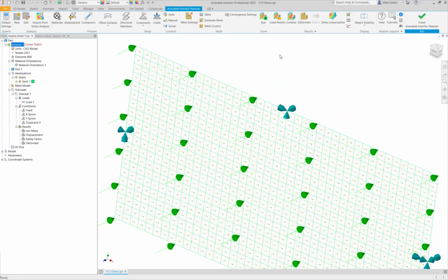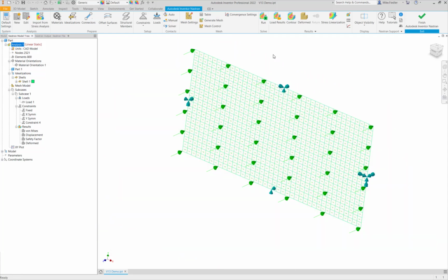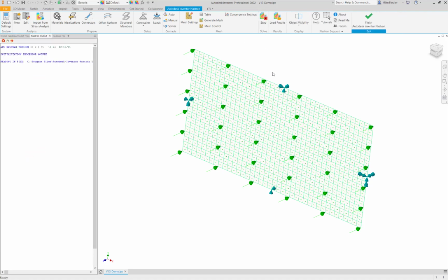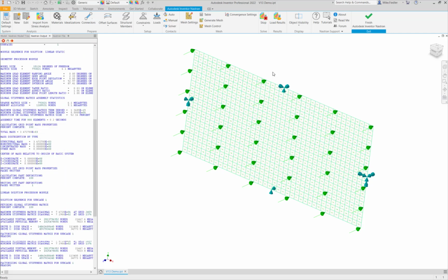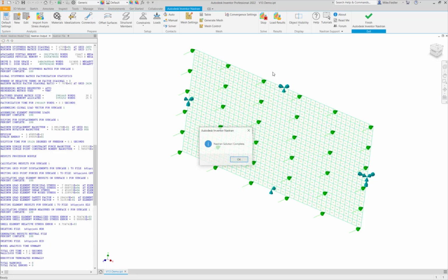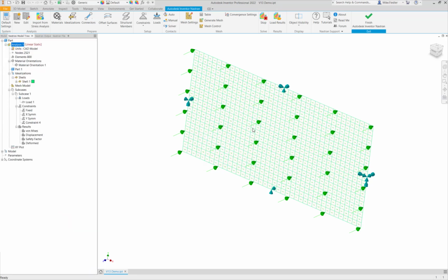So that just makes it a little bit easier, I guess, to keep straight when I'm looking at the results, that when I look at the X tensor direction, it is in fact aligned with the global X, and then that would mean the V direction, or the Y tensor, would be aligned with the global Y direction, right? All right, let's go ahead and run that again, just in case that wasn't what the program had chosen. Could be a mismatch. We don't know what the program would have utilized before because we hadn't defined it.